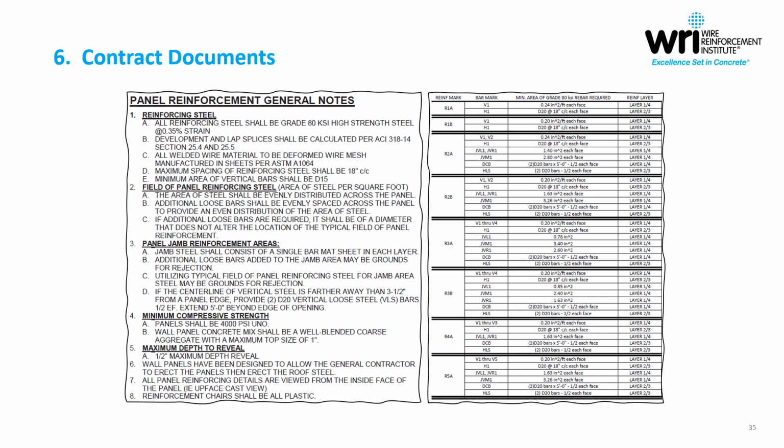Now, the horizontals, the engineer has gone ahead and specified it to be welded wire reinforcement, so it stands to reason that the verticals could quite easily be handled, and likely should be handled, with wires as well. But it's really kind of a progressive approach where the engineer of record is, instead of saying a quantity of rebar or a quantity of wires for the structural reinforcement, which in this case again is all the V prefix reinforcement, they're simply defining steel areas, which is kind of a nice way to handle it. It gives the contractor and ultimately their vendors some options as to how to help achieve the design intent.